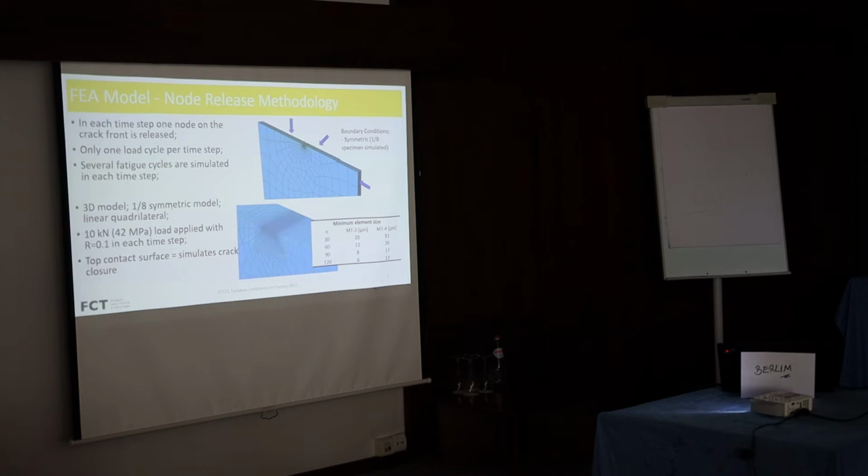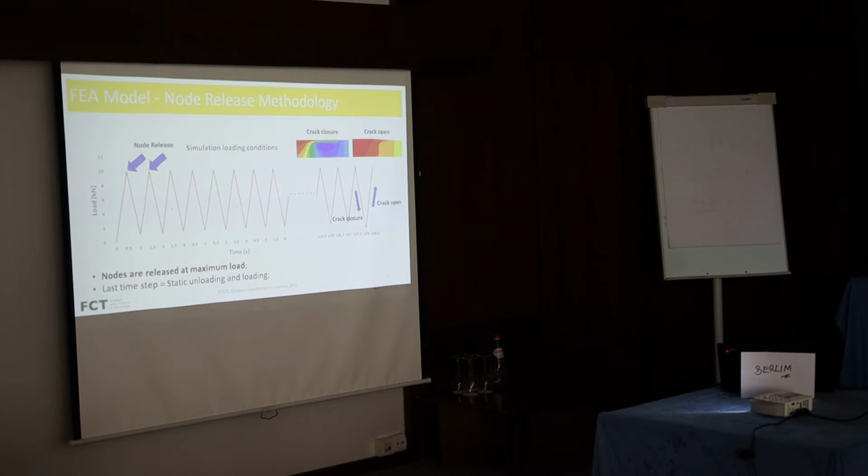In terms of boundary conditions, we consider only 1/8 of the specimen because we have symmetry in this kind of specimen. We applied 10 kilonewtons with a stress ratio of 0.1 in each time step. We performed a mesh convergence analysis, and we defined the number of elements equal to 120 because we obtained stable values for both the specimen MT2 and the specimen MT4.